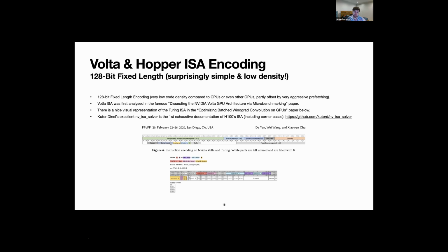And the barrier mask is making you wait for those barriers to be satisfied. So if it's set on an instruction, that instruction cannot execute until the previous instructions that incremented those barriers are fully finished executing. The stalls are the mechanism for arithmetic instructions like FMAs and integer addition and so on, which is more of a fixed number of cycles, which the compiler has to figure out when is the best case that it could possibly execute.